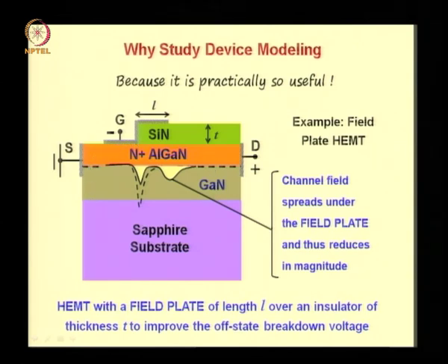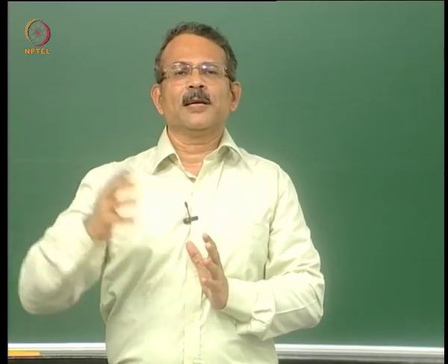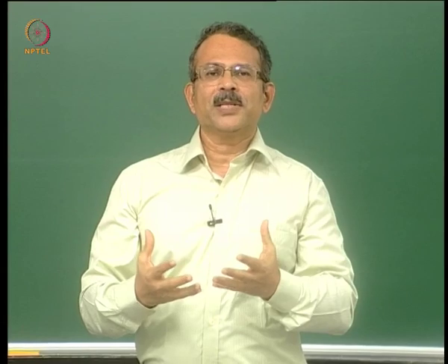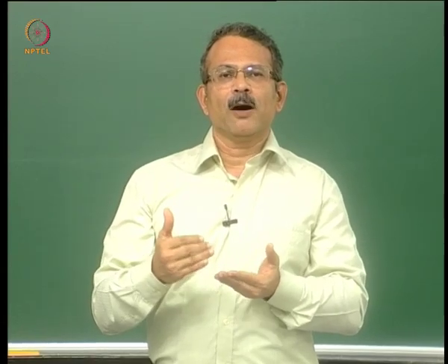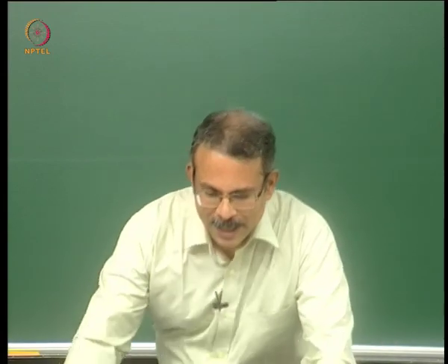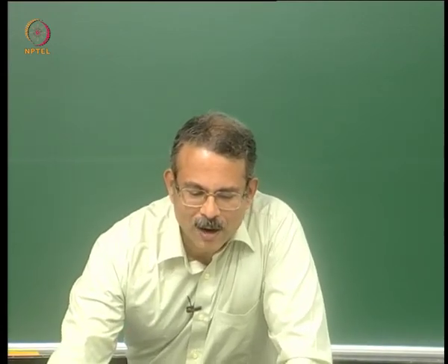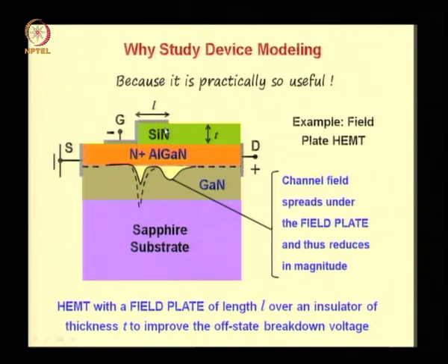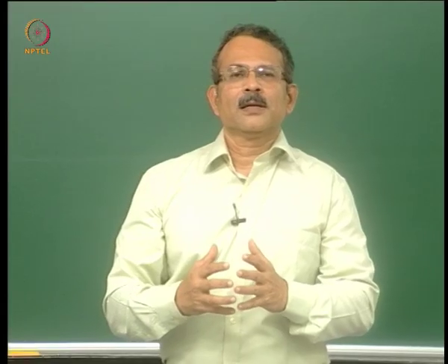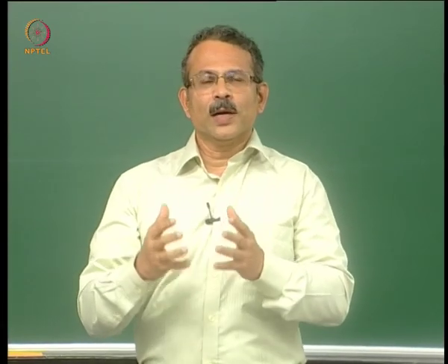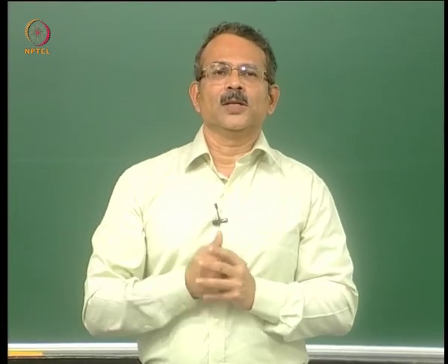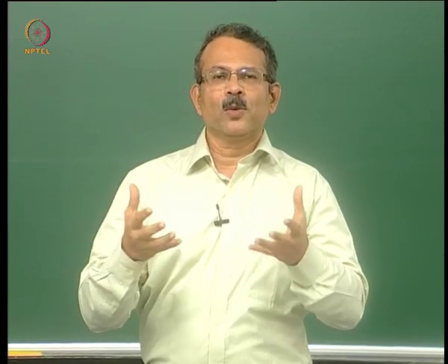However, when the simulation showed that you can get 200 to 300% enhancement, then there was a motivation to develop the technology of depositing this silicon nitride film of sufficiently large thickness to get the maximum potential out of this particular structural modification. So this is an example where the simulation helped you to work on the technology and improve it, so as to achieve improved device performance.